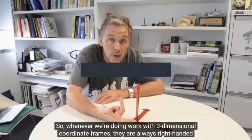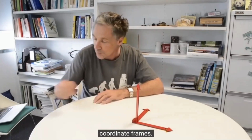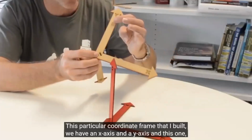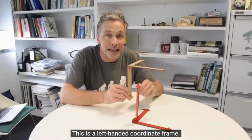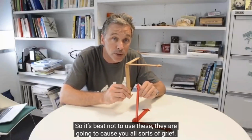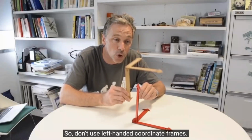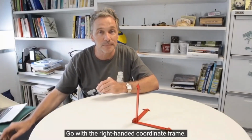So whenever we're doing work with three-dimensional coordinate frames, they are always right-handed coordinate frames. This particular coordinate frame that I've built, we have an x-axis and a y-axis, and this one, the z-axis, pointing downwards. This is a left-handed coordinate frame. So it's best not to use these, they're going to cause you all sorts of grief. So don't use left-handed coordinate frames, go with the right-handed coordinate frame.